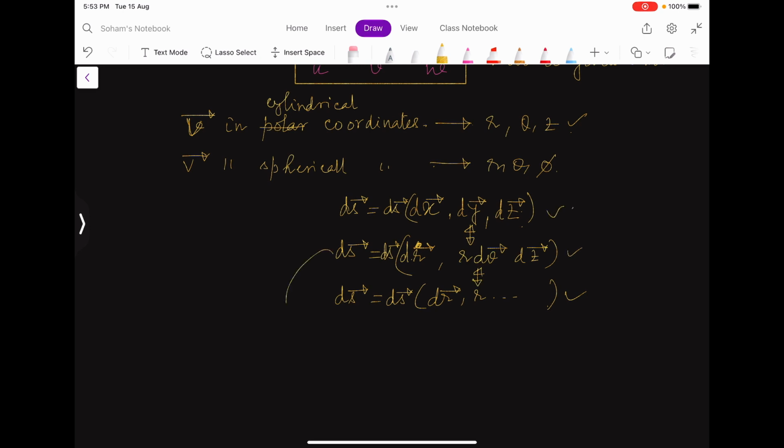And again, if I have to derive the streamline equation for the cylindrical coordinate, then let us have unit vectors along the three directions. Then I can have dr, r d theta, and dz, right? And now these are the lengths only because vectors are given. And again I have u, v and w, and that is equal to 0. This gives us the streamline equation in cylindrical coordinate.